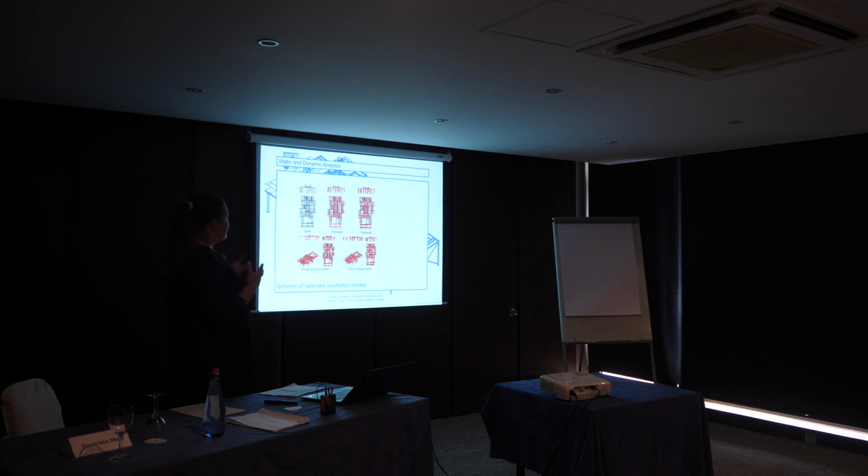And practically, why did we do this dynamic analysis? Because those robots move in several directions. They cause inertial forces, and thus they have oscillations at many frequencies. The frequencies of those robots could coincide with the natural free frequencies of the structure, and they will cause resonant behavior of the whole structure, and they will cause the failure in the end. So this was the second step.